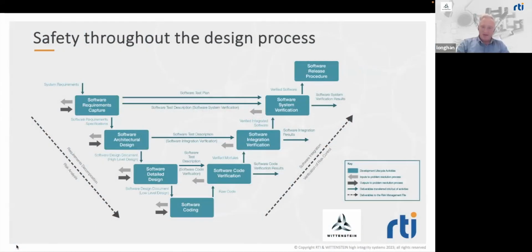Software implementing safety features must be highly deterministic and responsive to hazardous events, enabling the system to enter its safe state in the shortest possible time. SafeRTOS is a pre-certified, safety-critical real-time operating system for embedded processors. It delivers high performance and pre-certified dependability whilst utilizing minimum resources. SafeRTOS is based upon FreeRTOS. However, SafeRTOS is not FreeRTOS.